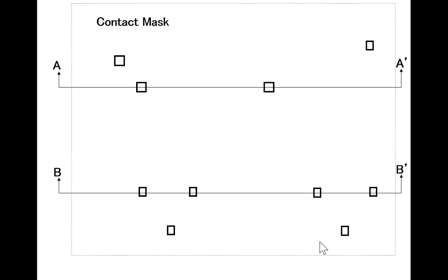Pardon? You said metal to metal for the vias? Yeah, vias for metal to metal. Metal 2 to metal 1. Metal 3 to metal 2, and so forth. Don't we make an M1P via? What about the M1P via? Isn't that metal 1 to poly? Metal 1 to poly, is that called a via, or is that called a contact? I don't know, it's in the vias on Cadence. So it must be a via then.